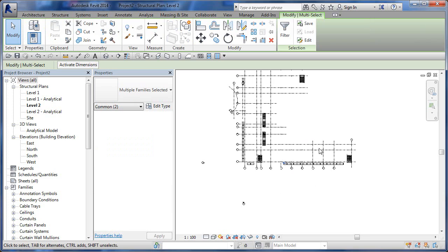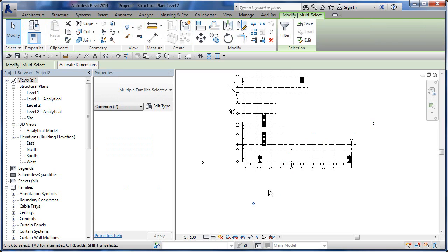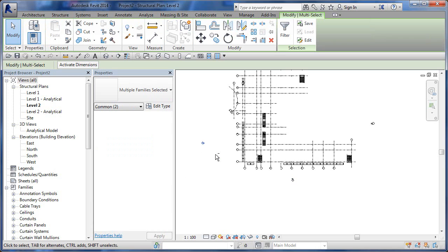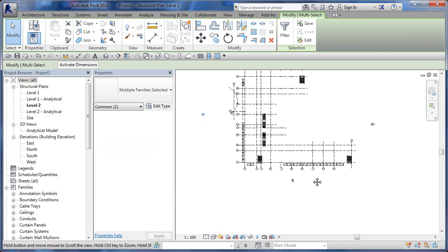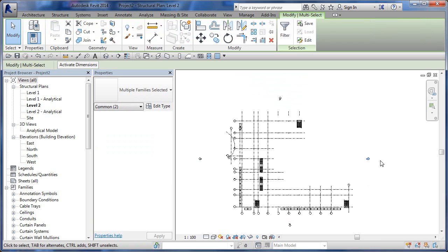Because this is one big link, I don't grab it using my shift key and my arrow key on my keyboard. I'm moving that over. Window box, shift on the keyboard, arrow key. If you don't use the shift, it's little nudges. If you use the shift, it's big nudges. Again, window box, nudge that guy over. So we just want to get our elevations in position first.